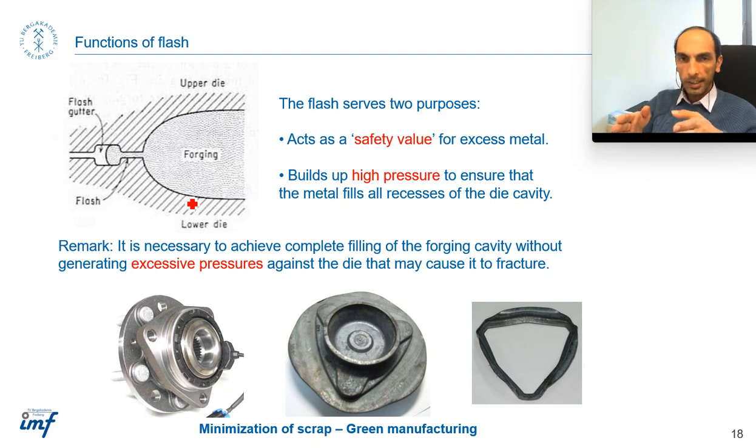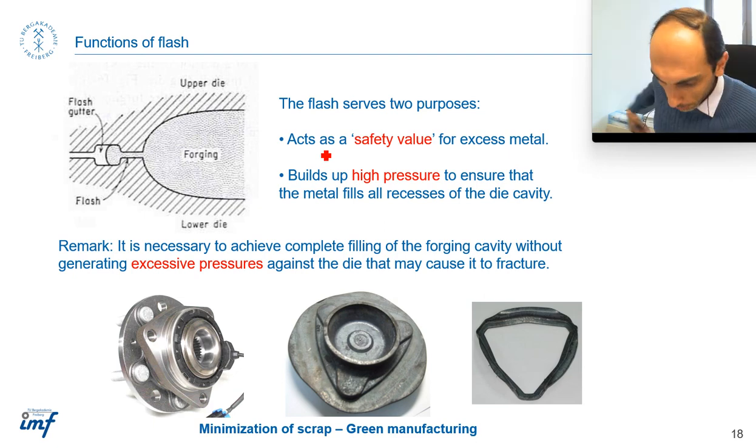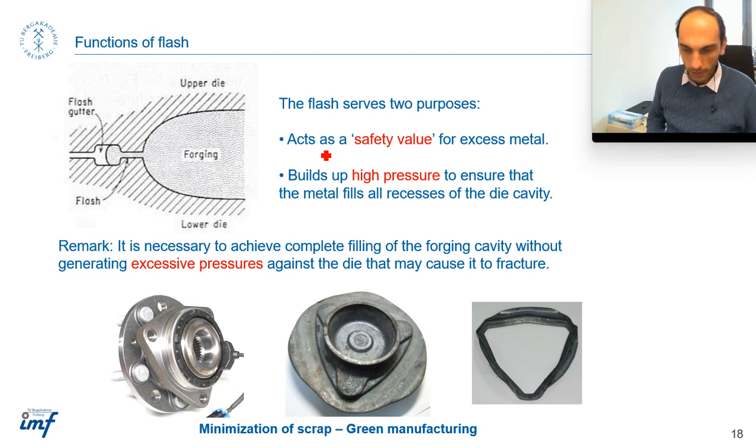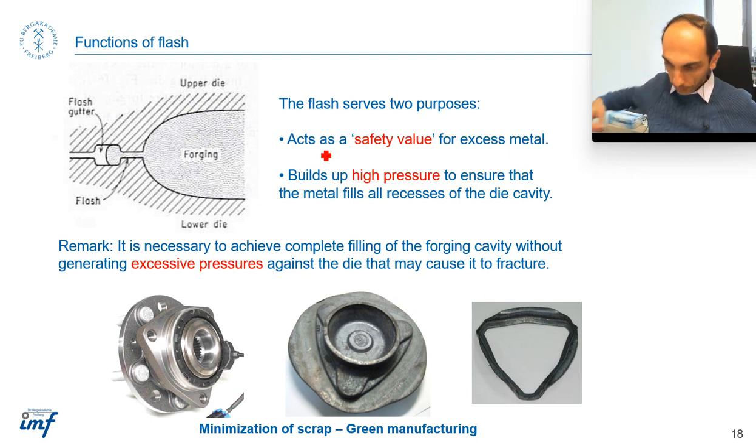In that case, if you do not have flash, then because the material is big and the cavity is fully closed, the material has no space to escape. And if the material is a little bit larger, a very high pressure will be applied to the dies, which leads to die failure. So if you design the flash, you will be sure that you will not have this type of die failure, or die breaking.